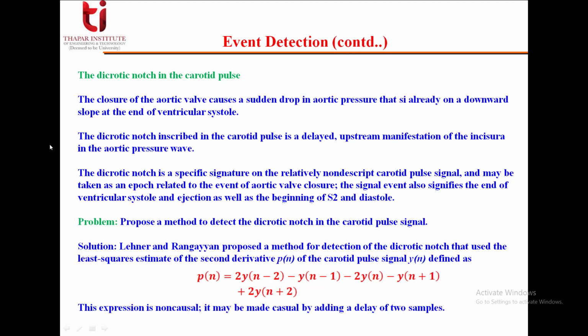If you see, it has y[n+2] terms, so this expression is non-causal. It may be made causal by adding a delay of 2 samples.